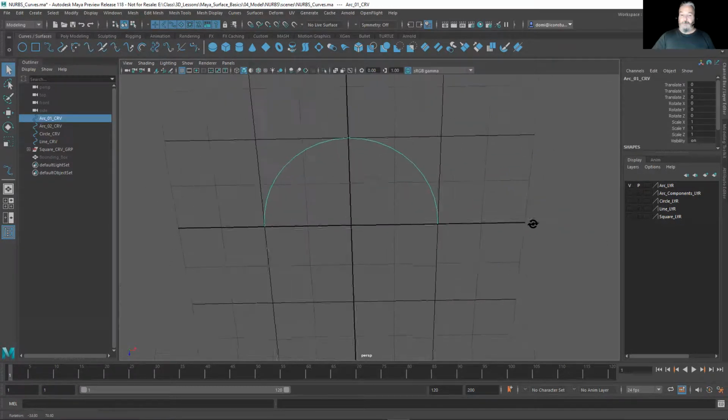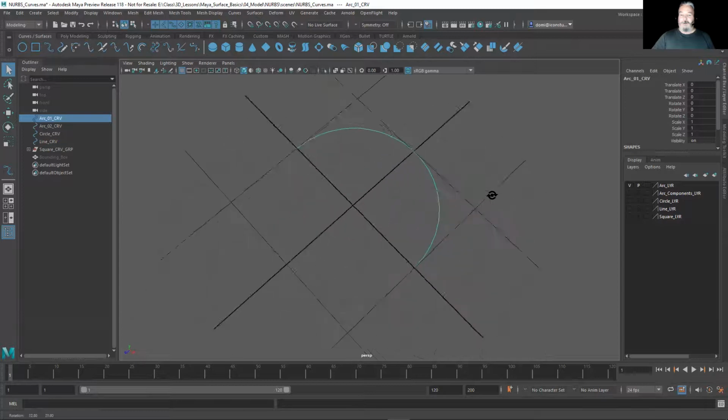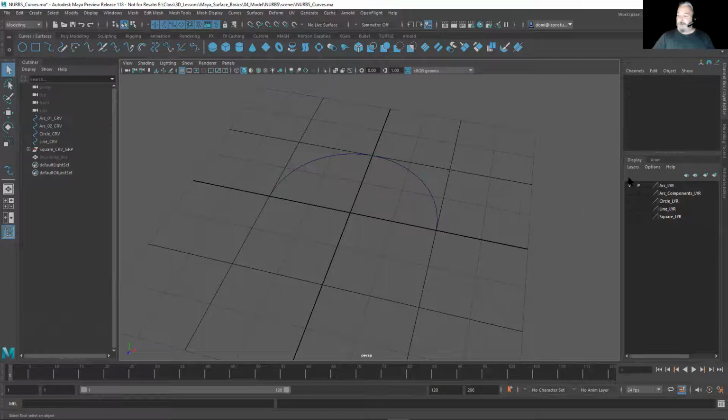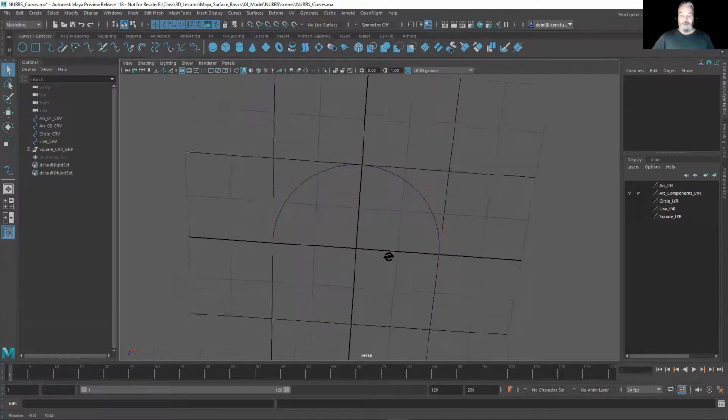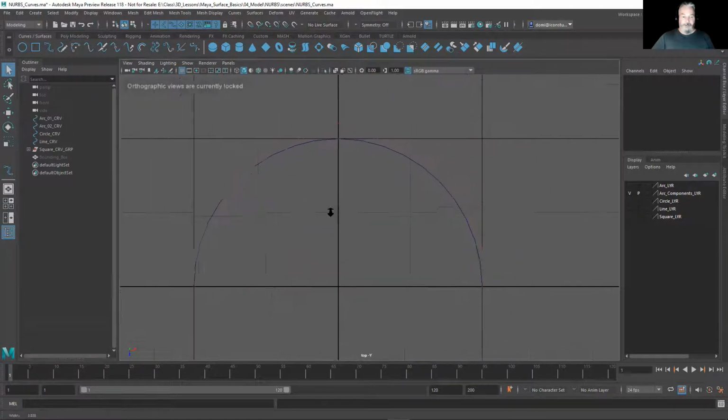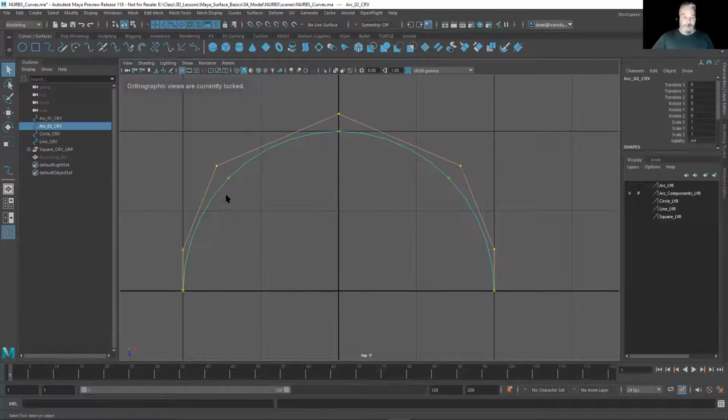So let me explain the elements of a curve, or what makes up a curve and how you can use them. I'm going to switch this layer off. I have one set up over here. These are the different elements of a curve. When you pick on this, this is the curve itself. But then you'll see these little points here. And these are the different elements of the mathematical representation of the curve that you can actually access and modify this curve with.